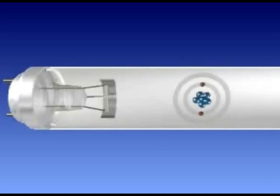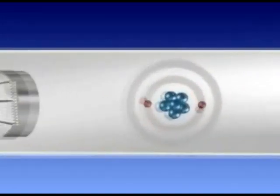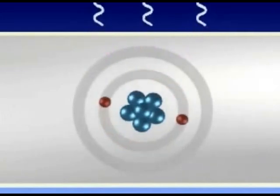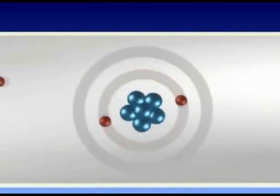Fluorescent lamps. These contain mercury vapor and inert gas. When current flows, the electrons hit the mercury atoms. Energy is transferred to the mercury electrons, pushing them into the higher orbits of the atoms. When these electrons flow back to the original orbits, they release this energy in the form of UV radiation. The UV is converted to visible light by phosphor coating on the inside of the glass bulb.